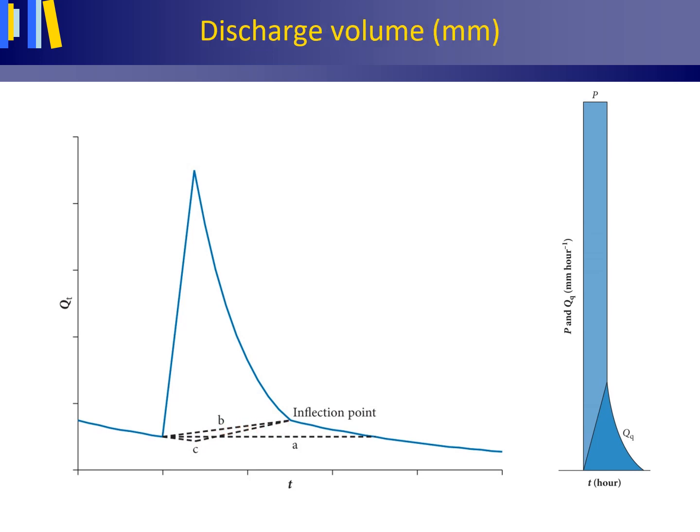Similar to precipitation depth and evaporation, the discharge volume of a river may be presented as a length unit, for instance, millimeter. Discharge volumes in cubic meter can simply be converted to meter by dividing by the total drainage basin area in square meter. Multiplying this result by 1000 millimeter per meter, of course, delivers an answer in millimeter.